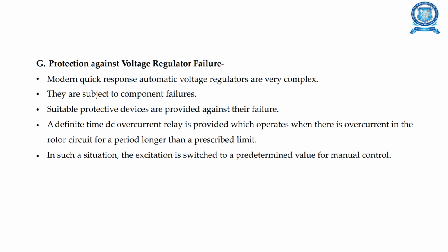Protection against voltage regulator failure. They are subject to component failures. A definite time DC overcurrent relay is provided, which operates when there is overcurrent in the rotor circuit.